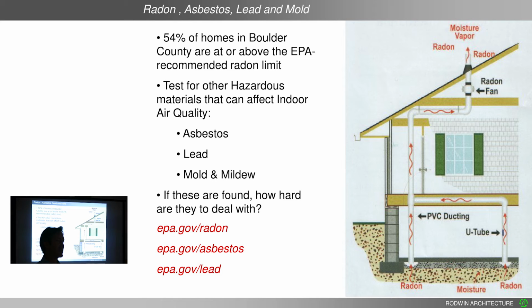It's an easy thing to test for. You go to any hardware store, or at least McGuckin's has it, little packets, and for $10 you can get a radon testing kit. You open it up, put it in the basement, and in 48 hours you know if you have elevated levels of radon. Radon is carcinogenic, and it is very serious, particularly if you smoke. It bonds with nicotine molecules and lodges in lung tissue, so it causes lung cancer like crazy.